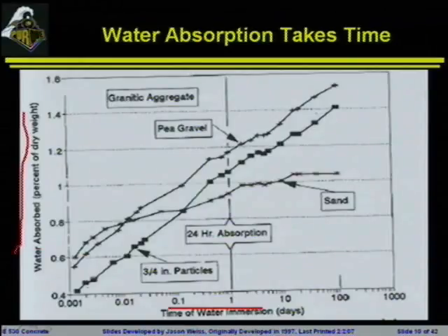And one of the things that I think is interesting here is you will notice that very, very quickly there's a considerable amount of water that gets sucked into the aggregates, into some of those pores. But over the course of the rest of the time that those aggregates are being saturated, this amount of water absorption is increasing. We arbitrarily, or somewhat arbitrarily, choose a 24-hour value, and we say that this is how we're going to define things according to ASTM.